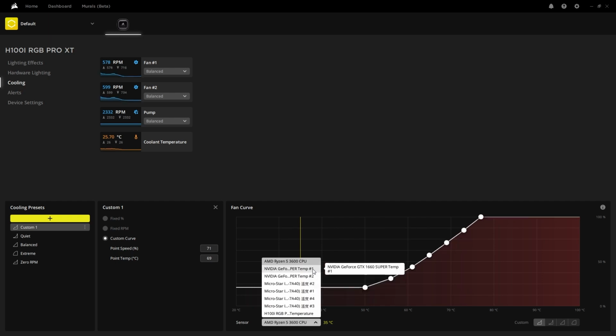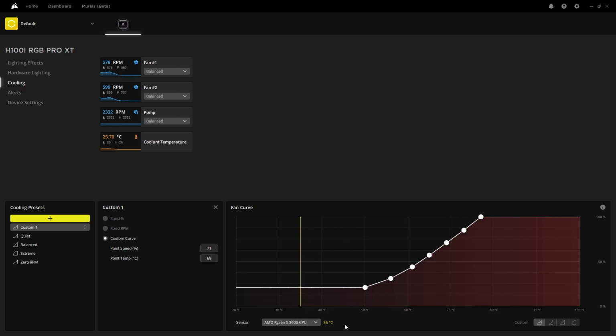So which one is better, using the CPU temperature or the water coolant temperature? I would say that if you use the CPU temperature, you can see the CPU temperature is indeed now 35 degrees and it actually varies a lot and is quite sensitive towards the workload. The range could be from 30 degrees to 80 degrees depending on the workload. And sometimes with a very sudden and short period of a heavy workload, the CPU temperature can drive towards a very high temperature in a very short period of time. So if it happens, then even though you have a reasonable fan curve for the CPU, it will suddenly increase the fan speed, which someone will actually feel is a little bit annoying at that time.